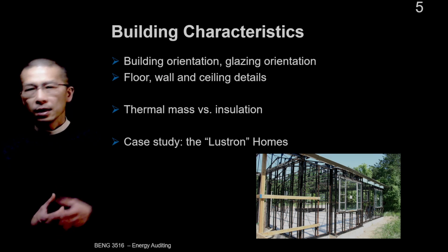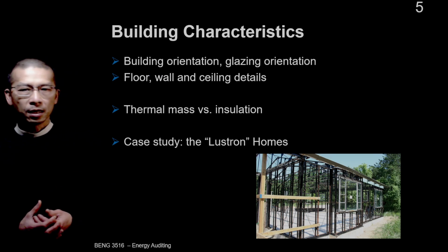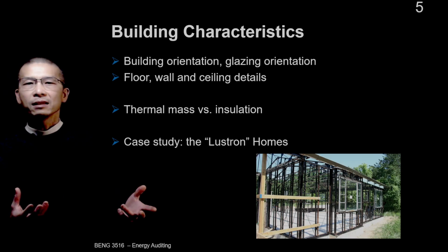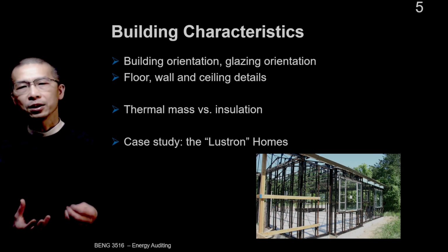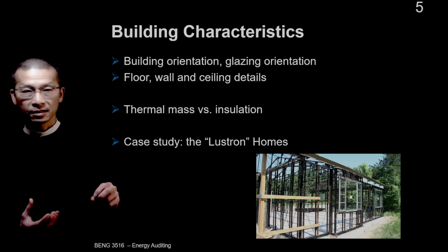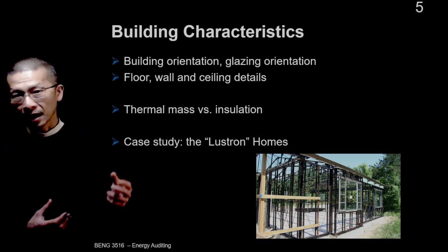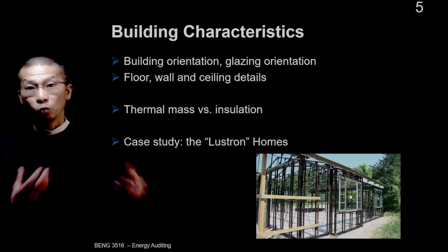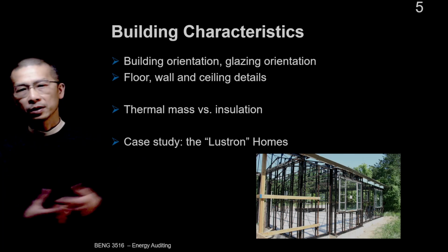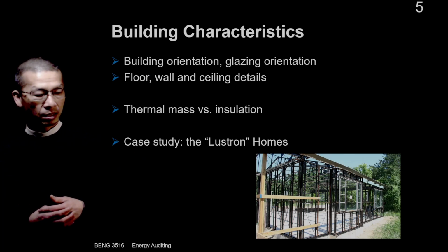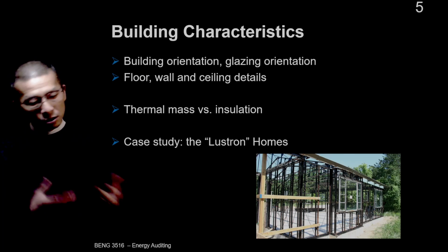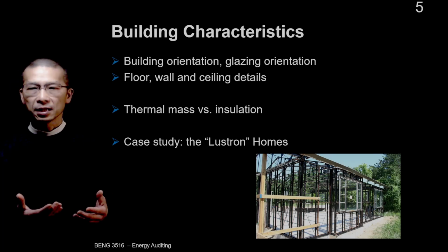So a high thermal mass building cannot use aggressive night setback on the thermostat because it will take many hours to warm that concrete back up in the morning, right? So lots to think about.